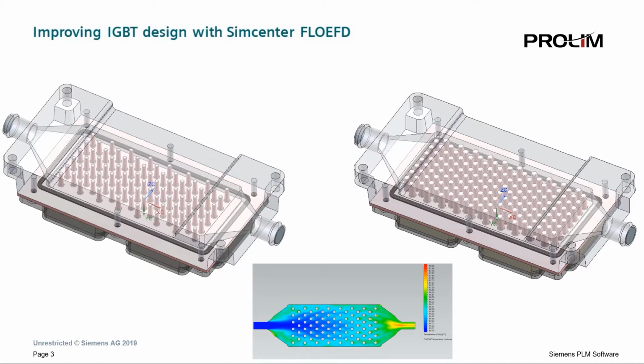Varying the pin size, draft angle, and pin pattern, we are able to get this new baseplate design through an intelligent design space exploration to minimize the IGBT temperature as well as the cooler pressure drop across. Let's take a look how we did this in FLOEFD.